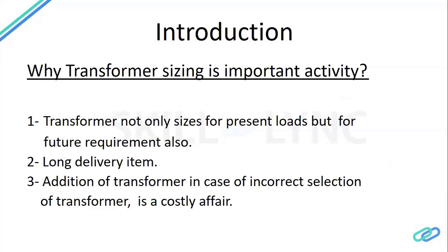When you size the transformer, you are not sizing only for the present loads. You have to keep the business growth in mind, what the future loads will be. Otherwise, you have to change the size of the transformer after some years, if you want to increase the size of the plant or the production capacity, or install more motors. Then you will be in a problem, and you have to install a new transformer. Second thing, the transformer is a big device.